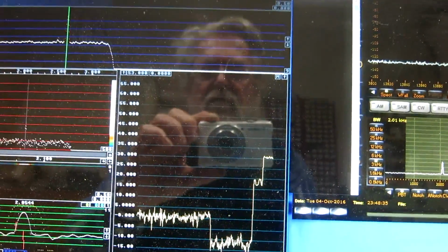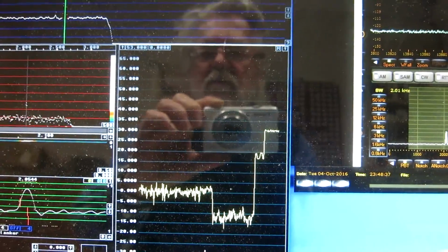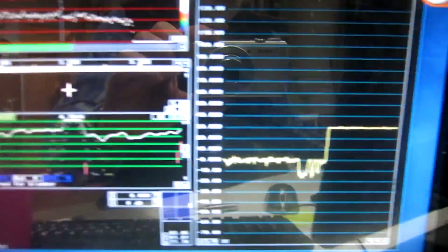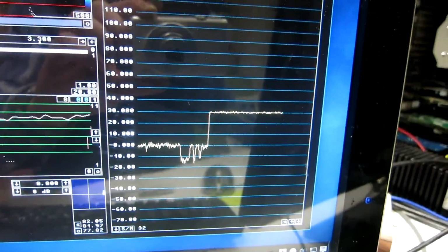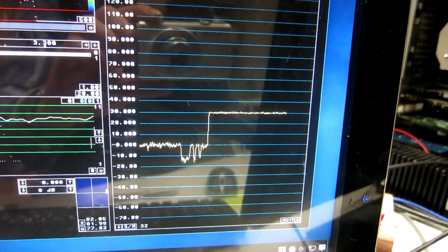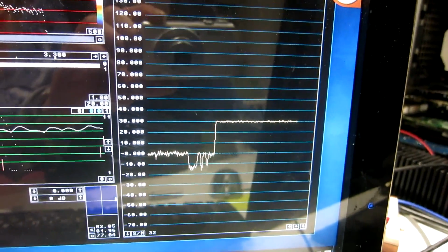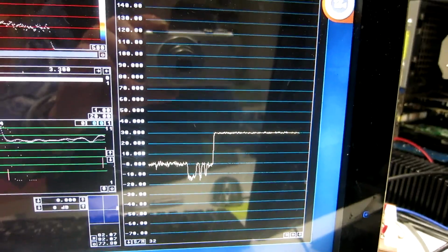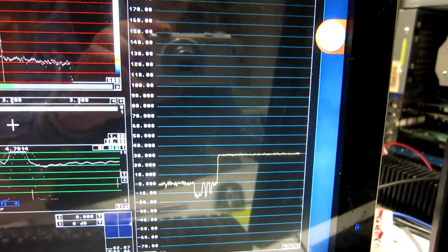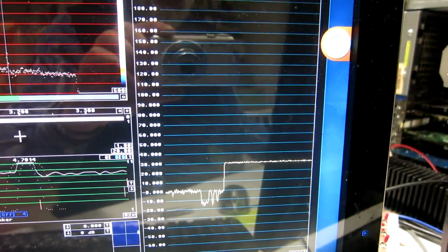And then I look at the signal to noise ratio. It's about 30 dB, and as it happens it's close to 30 dB also in the FT1000. This means the two radios have similar noise figures.